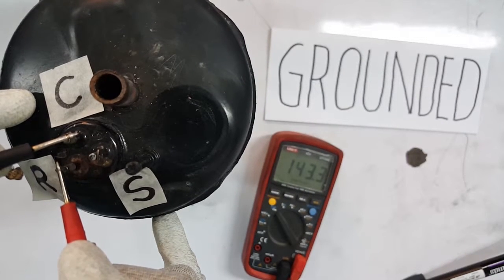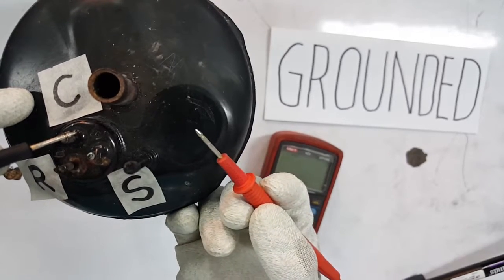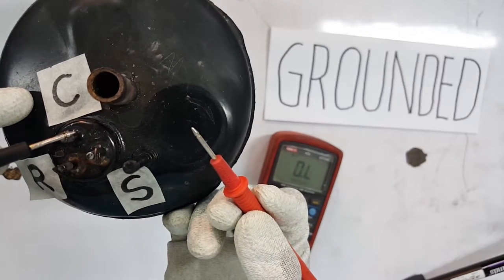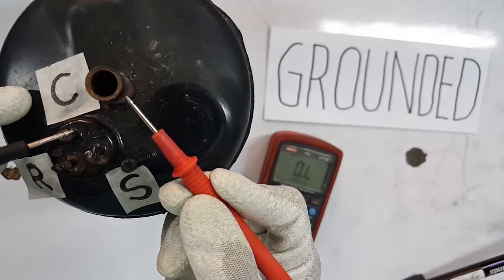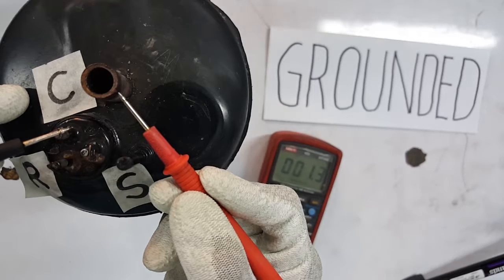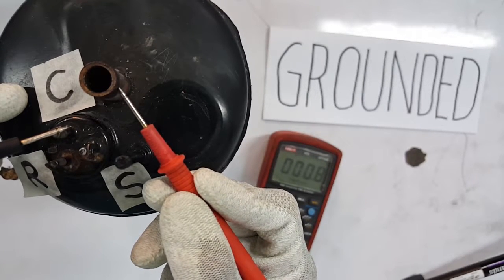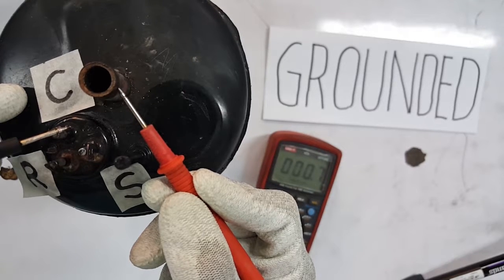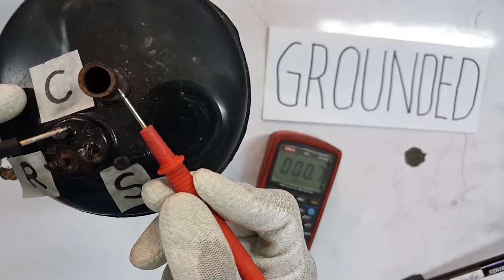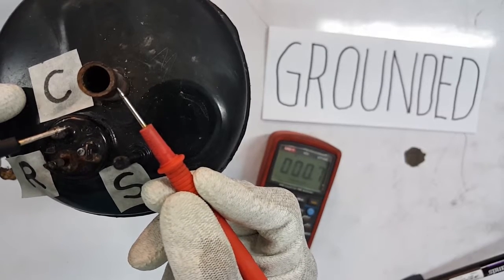And if you put one of the leads of our DMM on the body, any part of the motor compressor, then based on the DMM, we have 0.7. So this is an example of a grounded motor compressor.